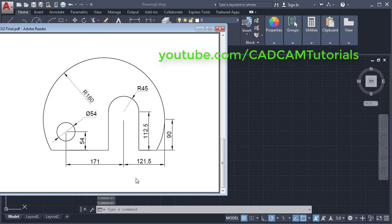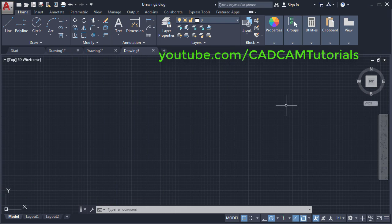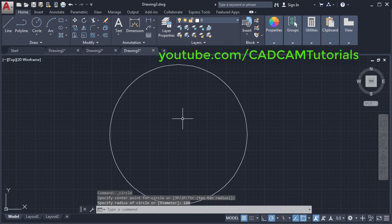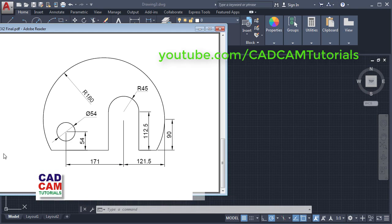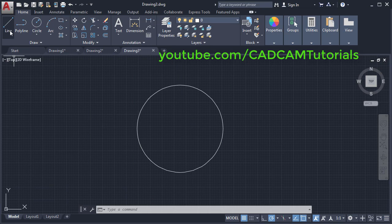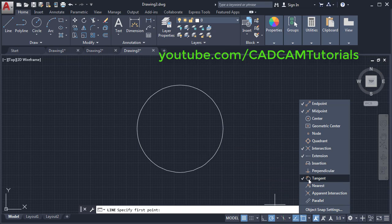Now here we will create this circle of 180 radius. Click on circle, give the center point, give the radius of 180, enter. Zoom it. Now here this horizontal line is at a gap of 90 from this quadrant point. Click on line, take your cursor to this quadrant. Now it is not showing the quadrant, it is showing tangent. So click here and cancel this tangent and turn on this quadrant and center.